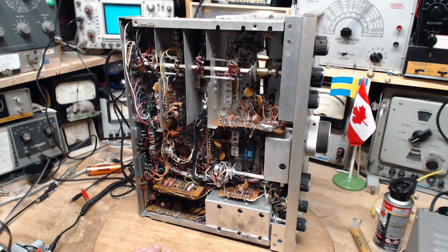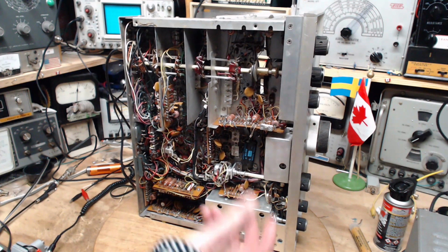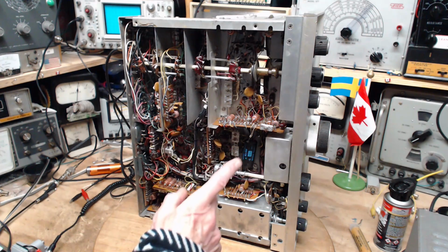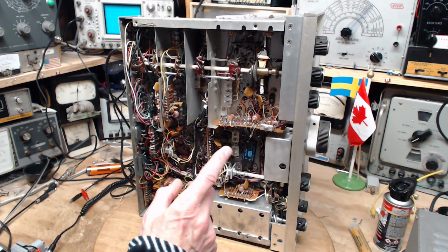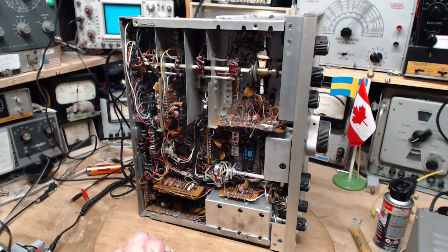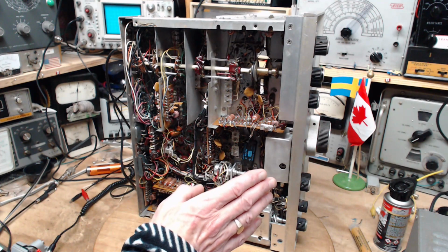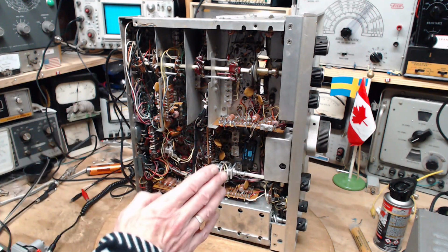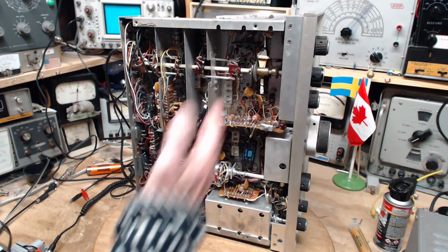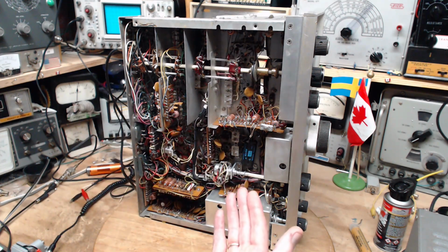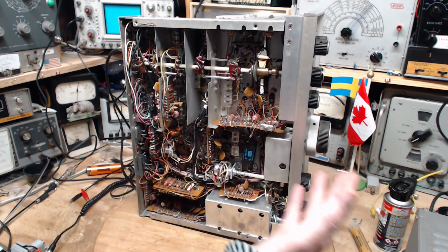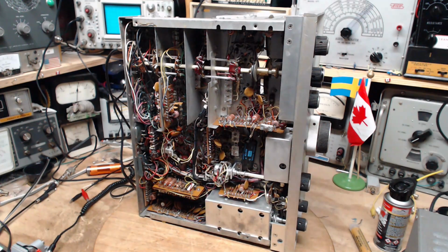It's derived from another, I was going to say transistor, but it's a transistor that's been wired as a diode, kind of like that. And the idea is, I think, when you forward bias this transistor diode, you then allow the passage of a heavy current, which causes a voltage drop, which drops the emitter voltage up here from where it is to below 11. Something like that is taking place, or supposed to take place.